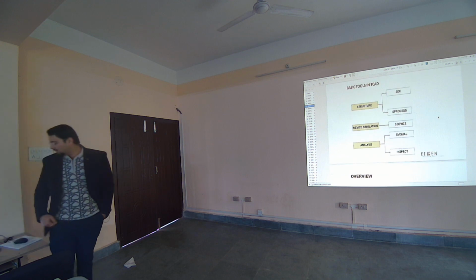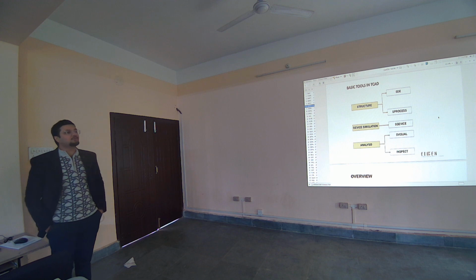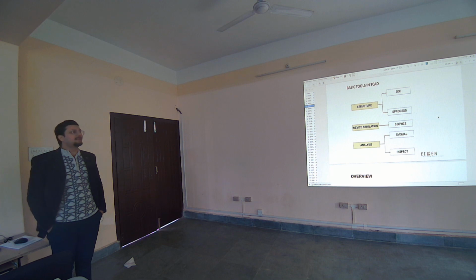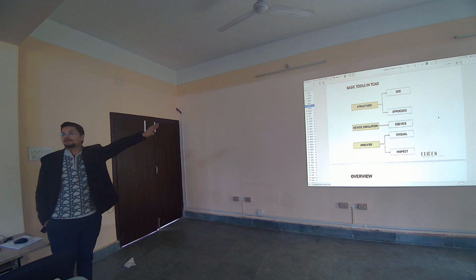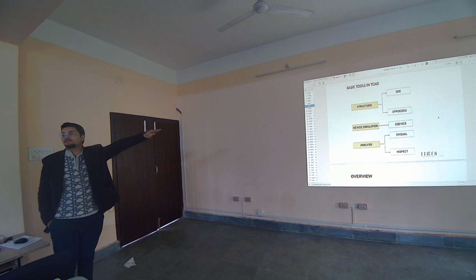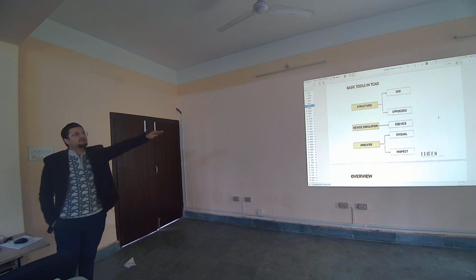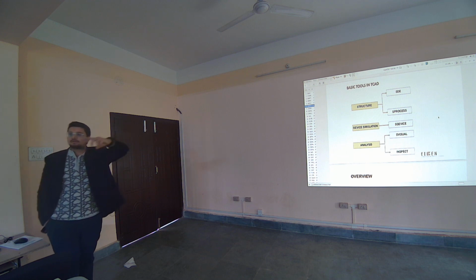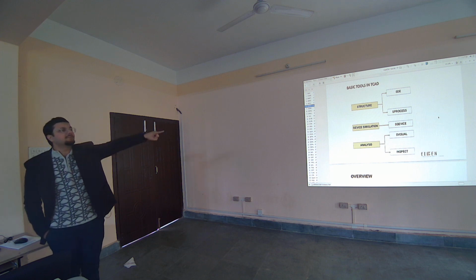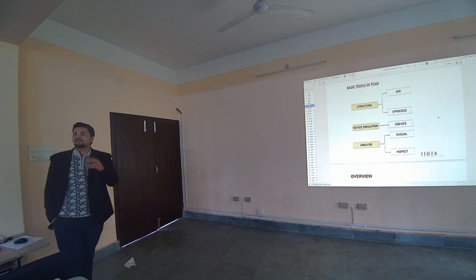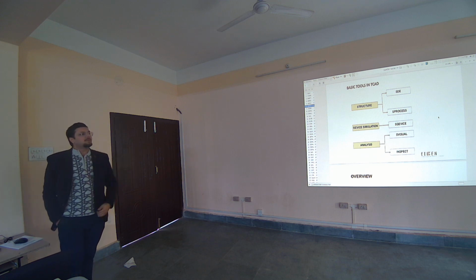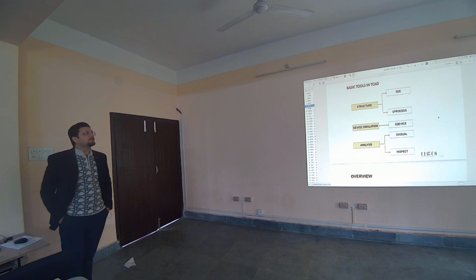Now the fourth one that we look at here is S visual. S visual and S inspect, both tools are responsible for analyzing what we have created already, right? So whatever we have created in the geometry, whatever kind of doping we have added, whatever the process that the device has gone through, and whatever the electrical, optical or any other behavioral changes that we have made in S device, if we want to analyze those, ultimately we need to get some results from that. So S visual is helpful in getting those results.